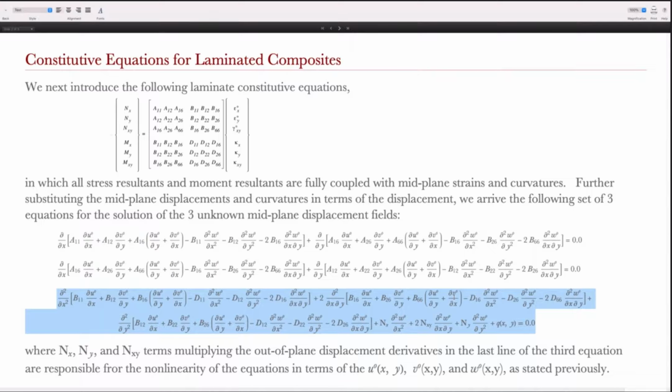So if I take a plate, a rectangular plate, these three equations are the equations that I need to solve for a given out-of-plane loading and some boundary conditions on the w's and in-plane displacements. You can solve the u, v, and w displacements out of these three equations. I don't think I can solve this using my Mathematica unless I go to a finite element method.